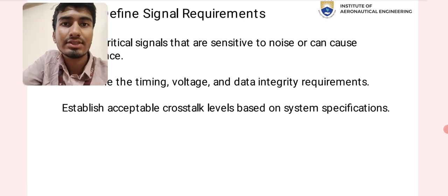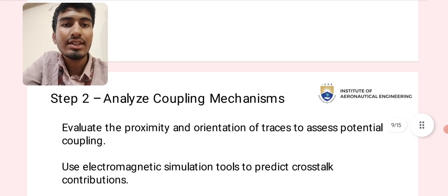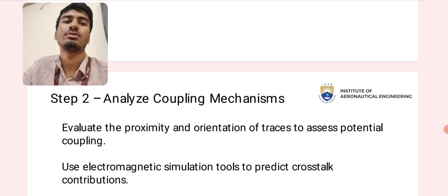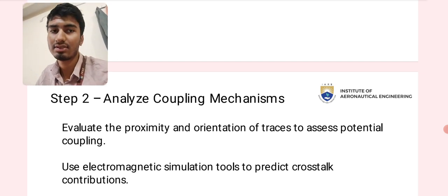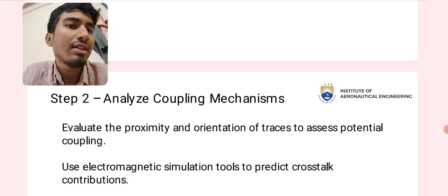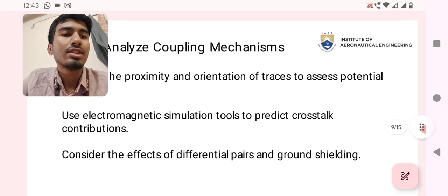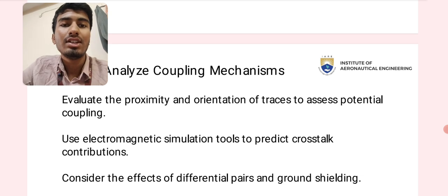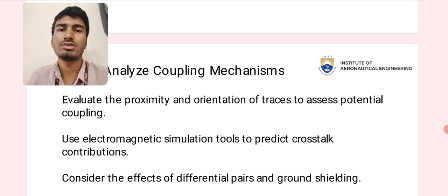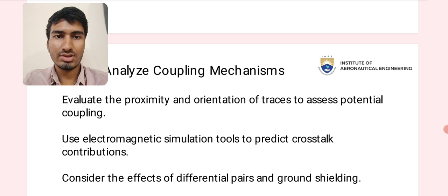Analyze coupling mechanisms. Evaluate proximity and orientation of traces to assess potential coupling. Use electromagnetic simulation tools to predict crosstalk contributions.